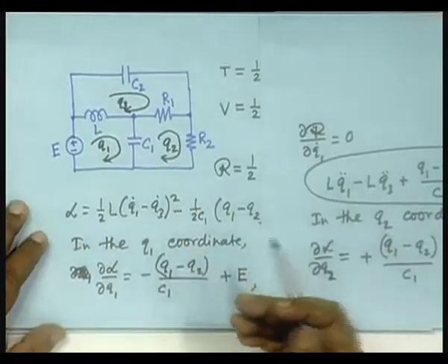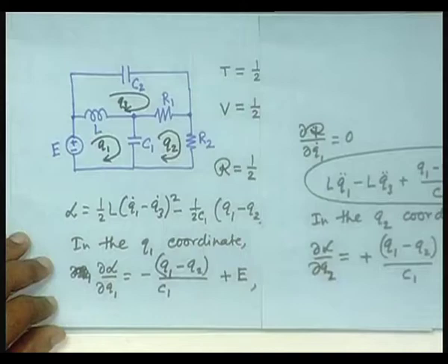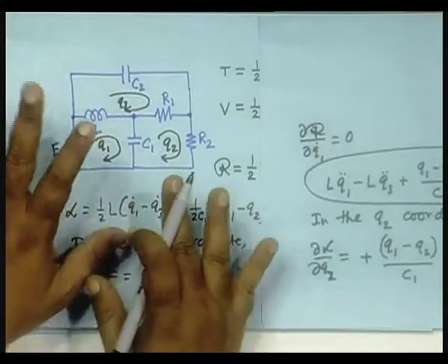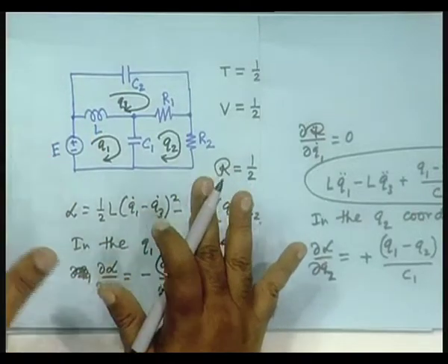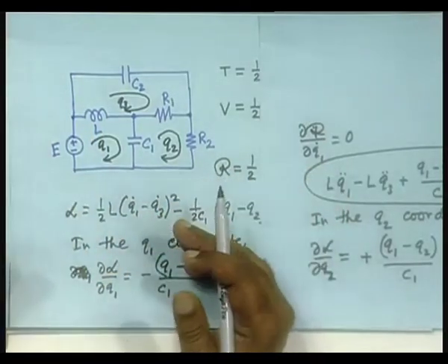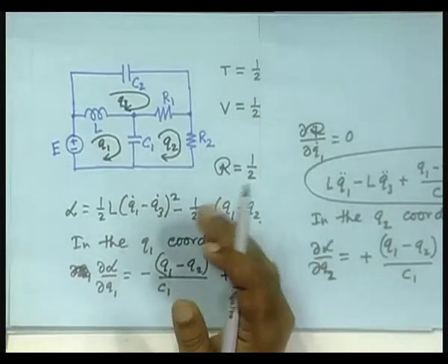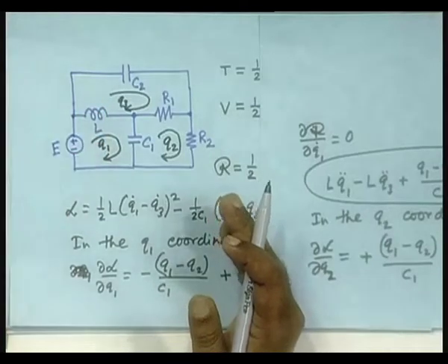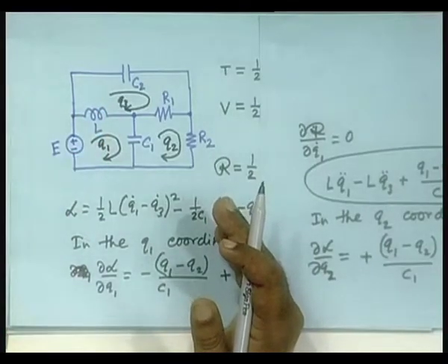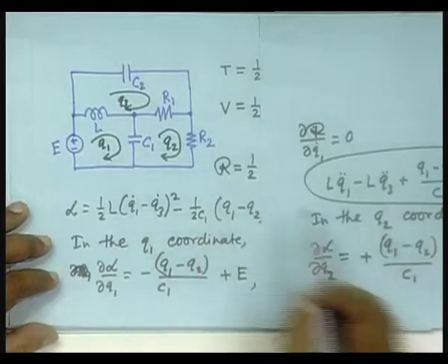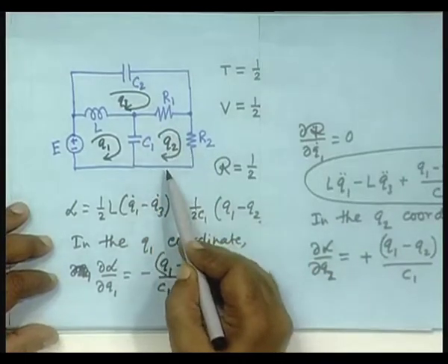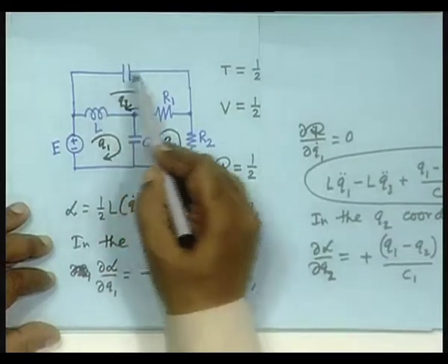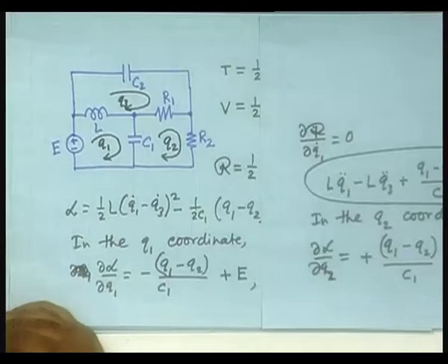And later we will also illustrate a more suitable method specifically devoted to electrical circuits, but you can easily see that the set of equations that we developed using mechanical systems as an example are equally applicable to electrical circuits, and they are not contradicting Kirchhoff's laws, which you know to be correct. Okay. Similarly, you can check that the second equation will actually be the KVL equation, Kirchhoff's voltage law equation, in the Q2 loop, and the third one is along the Q3 loop. Okay.